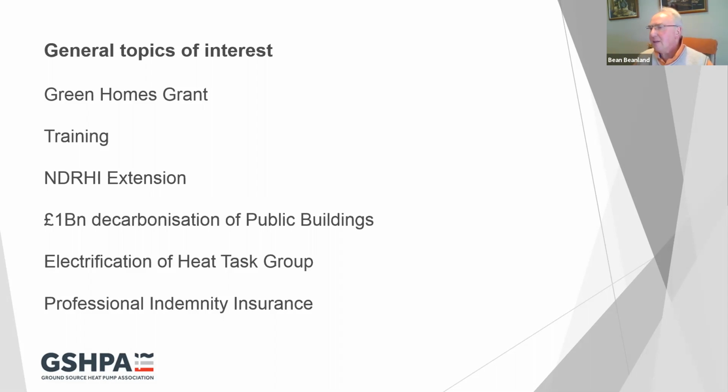And I think the missing bit that we haven't yet got across to people is that it is cheaper to go to a professional to get your borehole array designed than it is for an MCS certified installer to go out and pull a thermogeological report from a resource like the British Geological Survey and do the job themselves. The tragedy is we've seen lots of installers designing borehole arrays without the benefit of a thermogeological report, and clearly that's not design, that's guesswork. So does that answer? Yeah, absolutely.